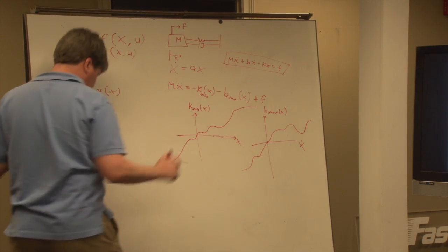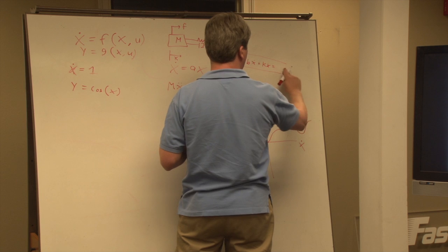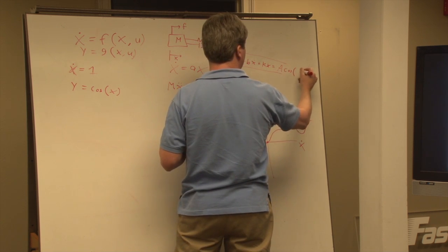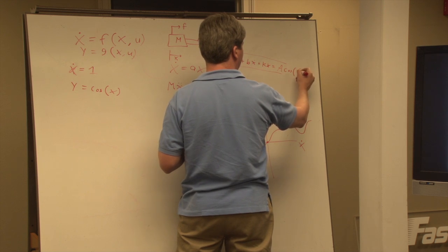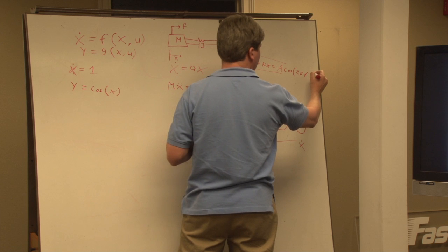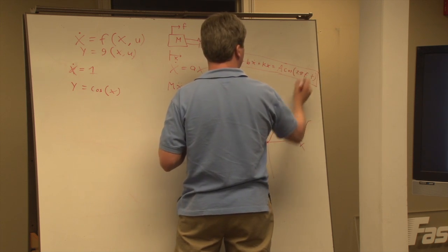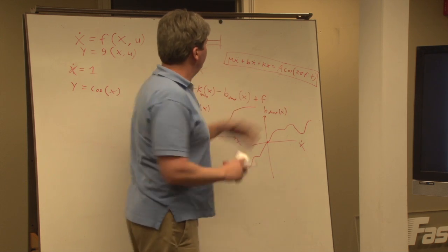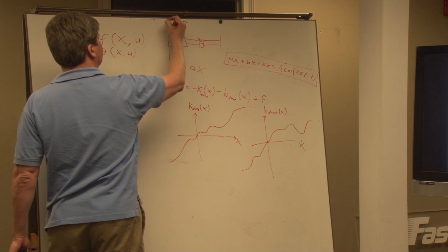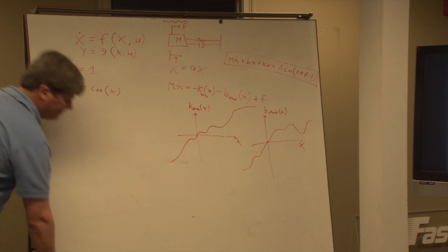What you assume in doing a Bode diagram is that your driving function is some amplitude, a sine or cosine wave, times some frequency. f would be in hertz, so put the 2 pi in there. We're going to drive this system with a force that's sinusoidal. So it's basically a measure of how resonant it is at certain frequencies.